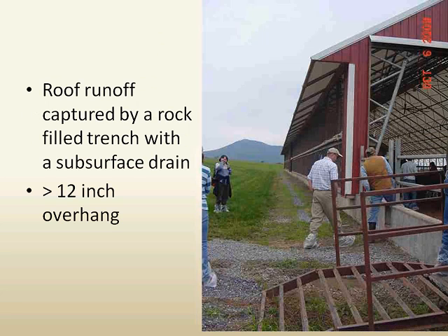And here's another picture, and if you notice, the roof line comes out, and where the water hits the ground, you can see where that action has actually created no grass growing right where the water is primarily hitting. In most cases, normally we want to see about a 12-inch overhang before you get to that gravel drain.